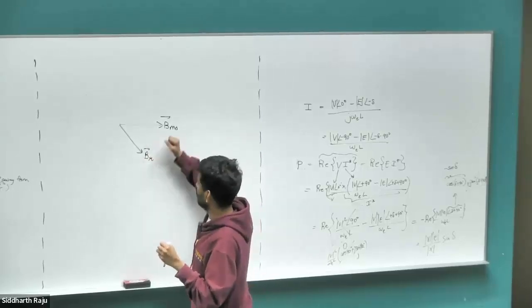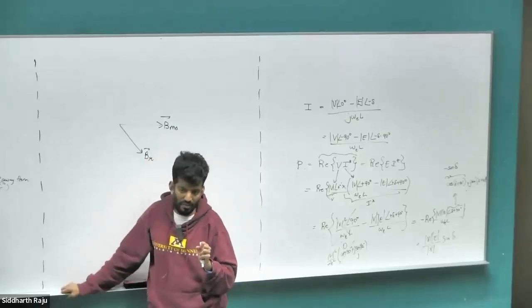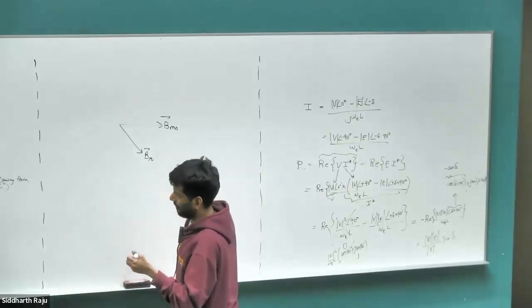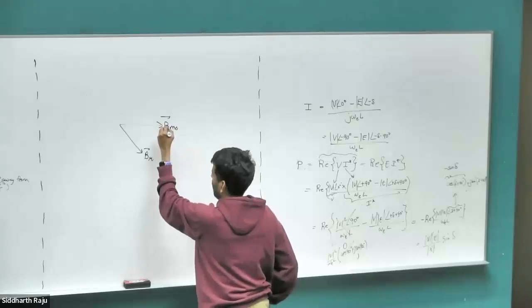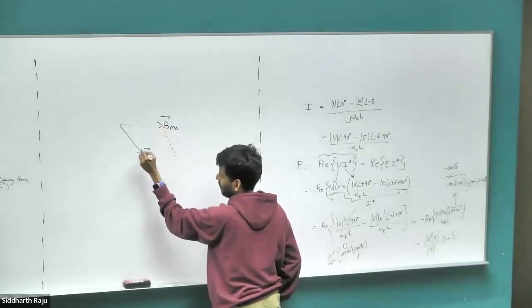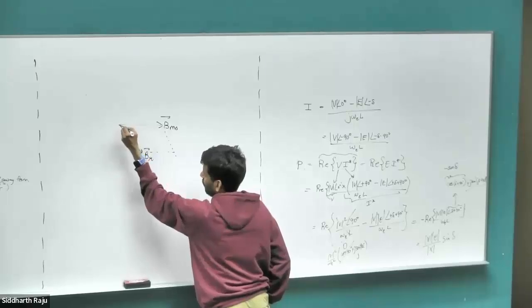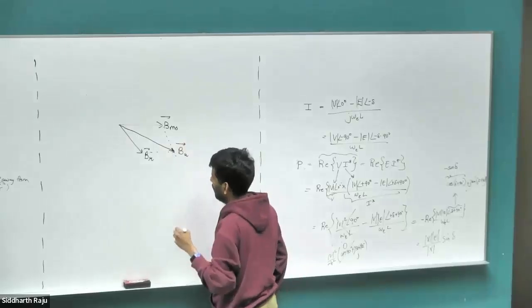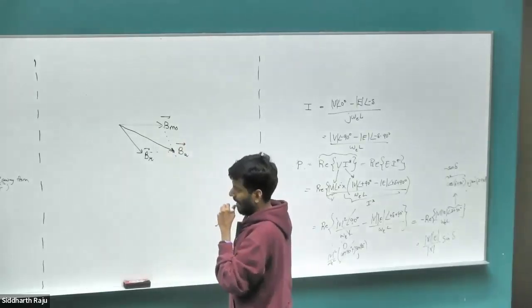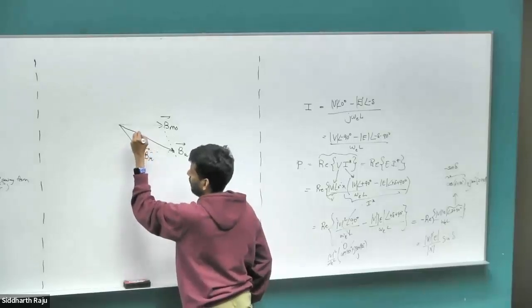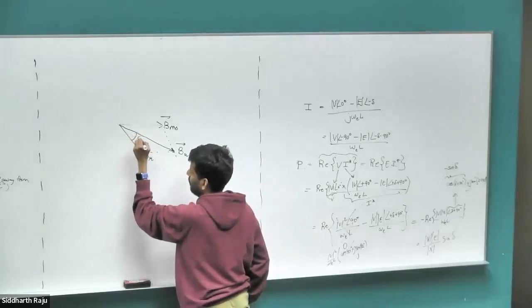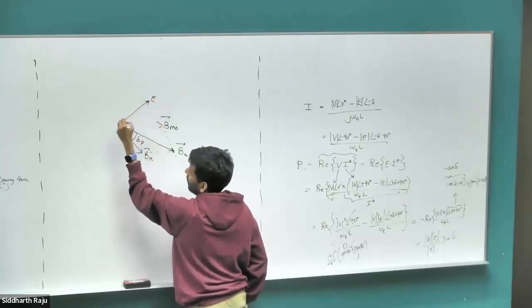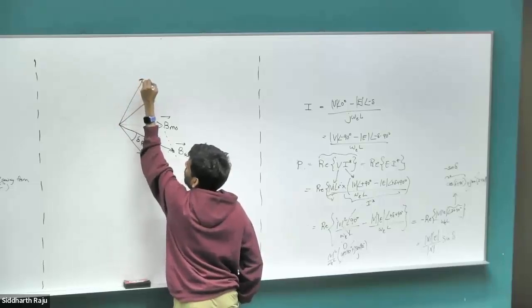Because in a permanent magnet synchronous motor, both of these magnetic fields exist at the same time in the air gap. So the sum of these two fields is what you can measure. And assuming that nothing is saturated, in an ideal case, superposition applies. So the net magnetic field you measure in the air gap would be the vector sum of these two. Let's call this BA space vector. So this is the net magnetic field in the air gap. And let me make a statement here and then we'll see why that is the case. The angle between these two would be the same, delta P, as the angle between the back EMF space vector and the terminal voltage space vector.